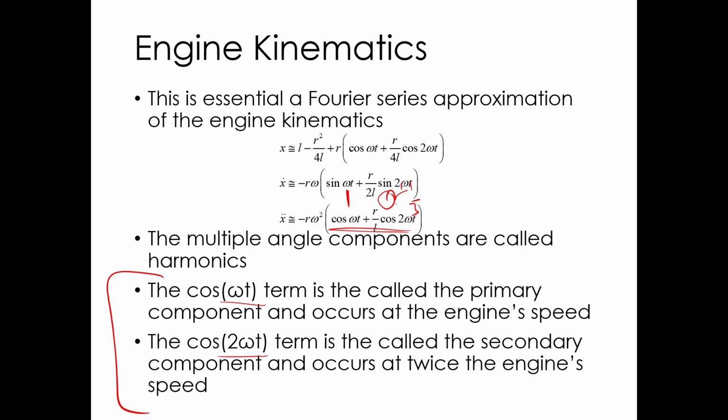And it gets back to some engines are perfect primary and secondary. I mean, straight sixes are perfectly canceled primary and secondary, at least in this theoretical framework we have here. So they're naturally inherently balanced. So some engines are good, some engines are less good. We'll talk more about that next lecture.